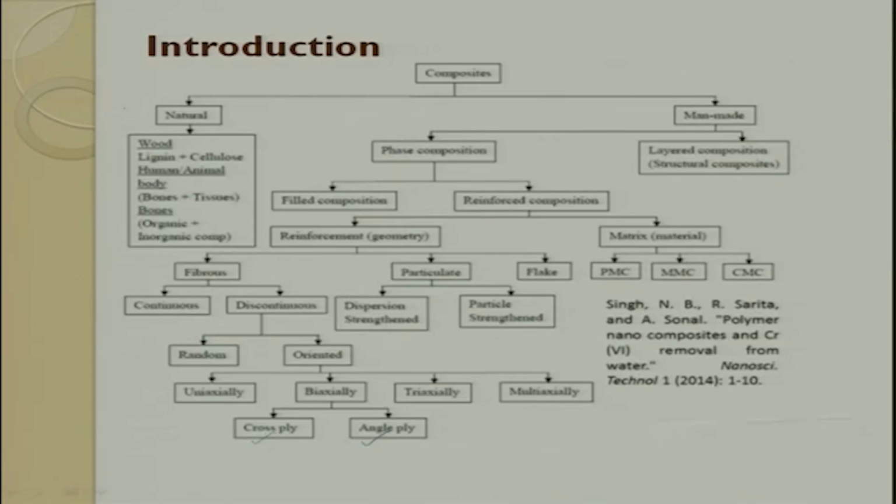So, when you look into this, now it is becoming very clear. Suppose I use a particulate type reinforcement, these particulates are basically ceramic material. So, this ceramic material is going to create friction between the tool and the workpiece. So, this has a higher effect. Same way when you talk about fibrous, glass fiber, ceramic material.